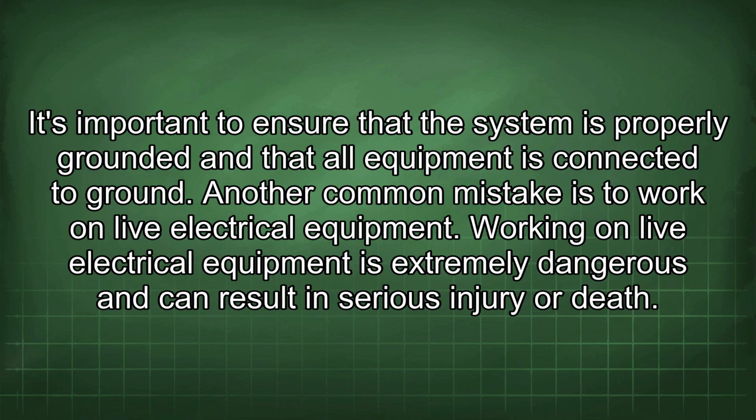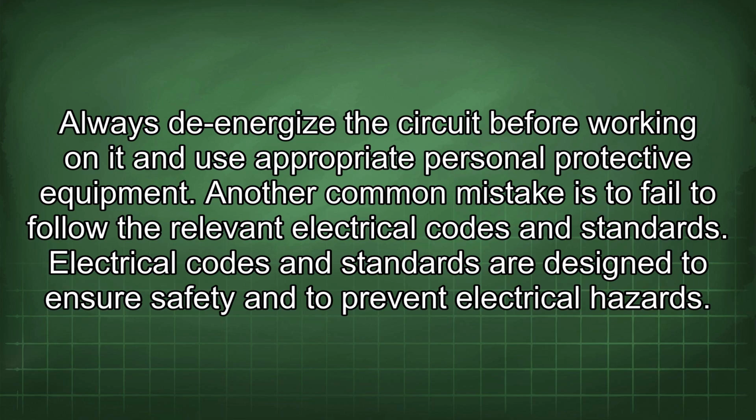Another common mistake is to work on live electrical equipment. Working on live electrical equipment is extremely dangerous and can result in serious injury or death. Always de-energize the circuit before working on it and use appropriate personal protective equipment.